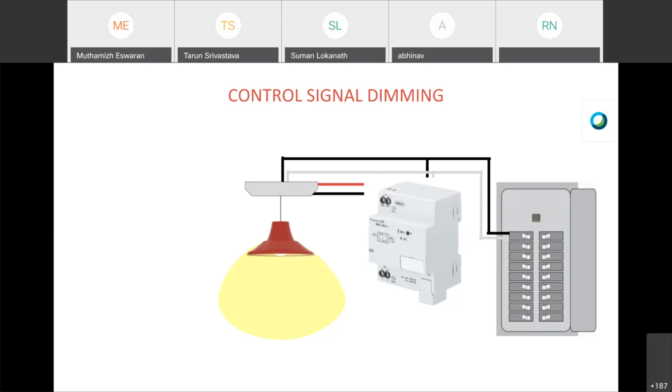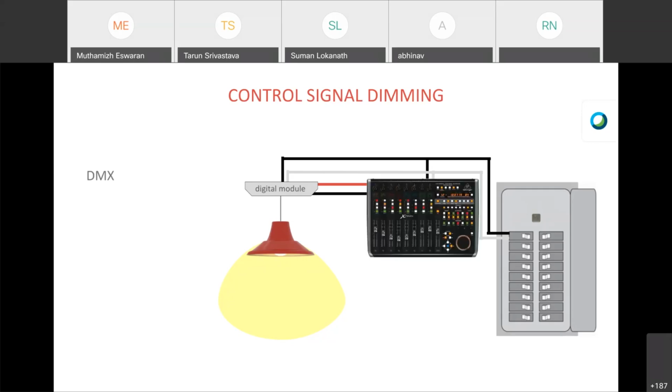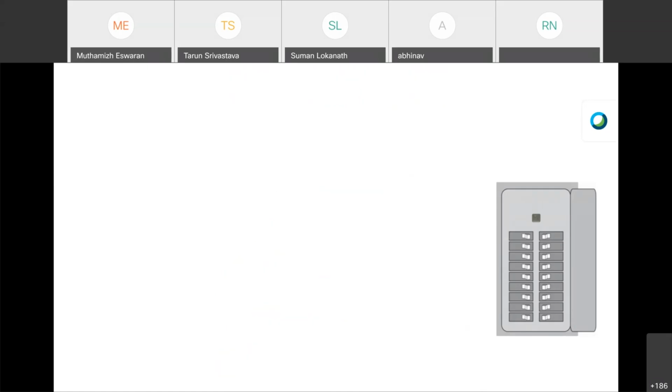And the last but not least one on the dimming is your DMX control, right? We don't directly integrate with DMX, and even for DALI we have control for KNX DALI, so we don't have direct DALI integrated with Control4. Okay, so your DMX module can connect to your DMX network, and then of course you need a third-party interface which can integrate into the Control4 platform. DMX is widely common for LEDs, which means color changing LEDs and other stuff, right?